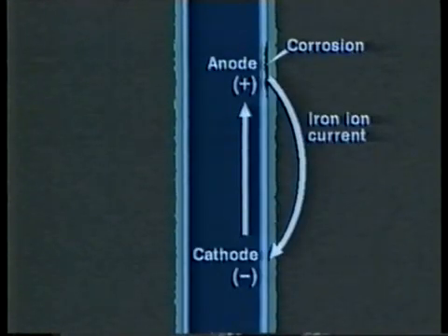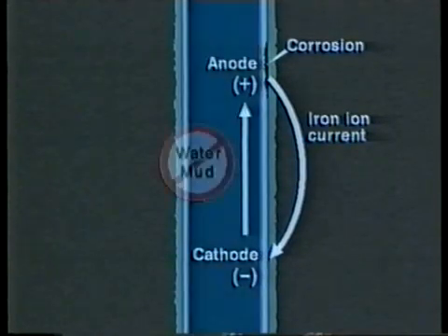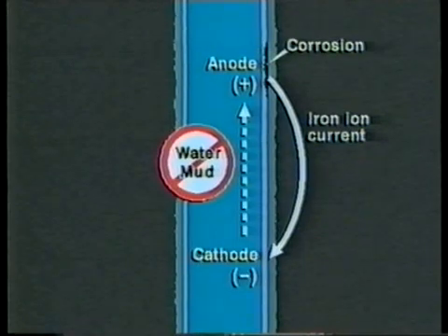Casing potential surveys detect electrochemical corrosion as it occurs by measuring the galvanic voltage it sets up. Those sections of the casing that act as anodes are undergoing electrochemical corrosion and metal loss. Casing potential surveys locate these intervals and indicate where cathodic protection can help to protect the casing. They must be run in an empty hole or in oil or gas. A conductor such as water or mud will provide a short which precludes interpretation.